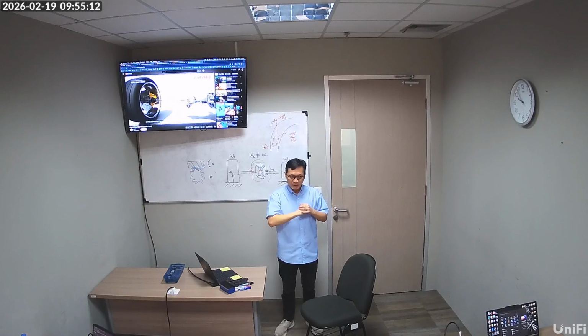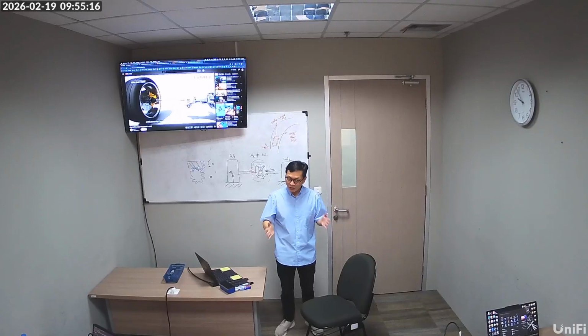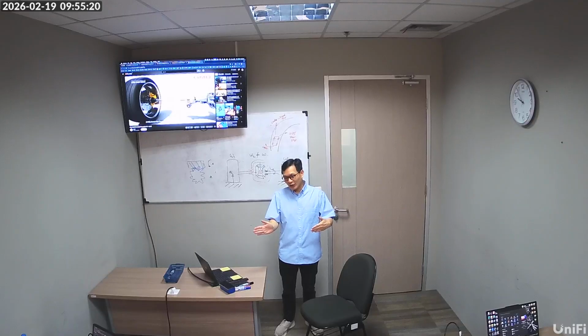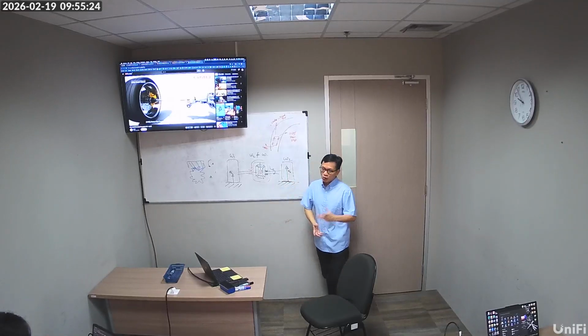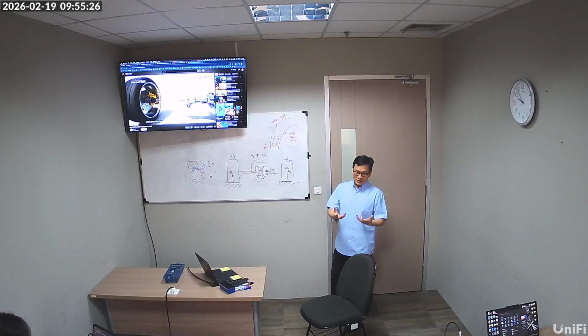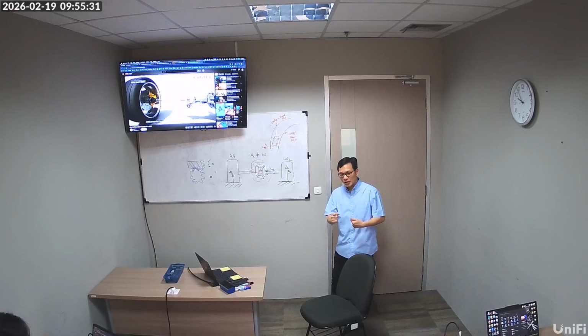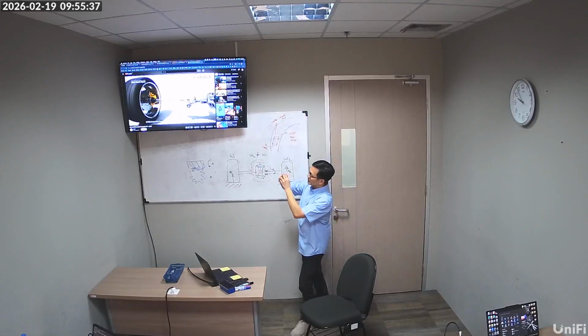The other extreme situation is in front-wheel drive. Because in front-wheel drive, it's not just the motion up and down, but you are turning and accelerating at the same time, which is usually when your CV joint burns out. That's when you hear it the most, right? You turn, you make an extreme turn, press the gas pedal, and you hear the clicking. And so, you know, all that comes loose or dry.